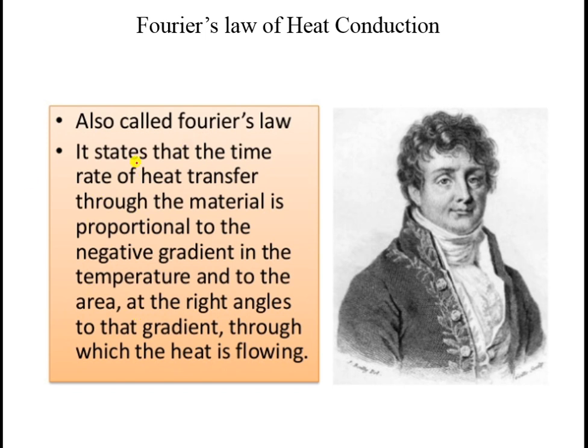Fourier has put forth one particular law related to heat conduction. It states that the time rate of heat transfer through the material, that may be solid or liquid, generally associated with slabs or along a particular wall, is proportional to the negative temperature gradient. The minus sign is used in that mathematical relation, and to the area at right angles to that gradient through which the heat is flowing.